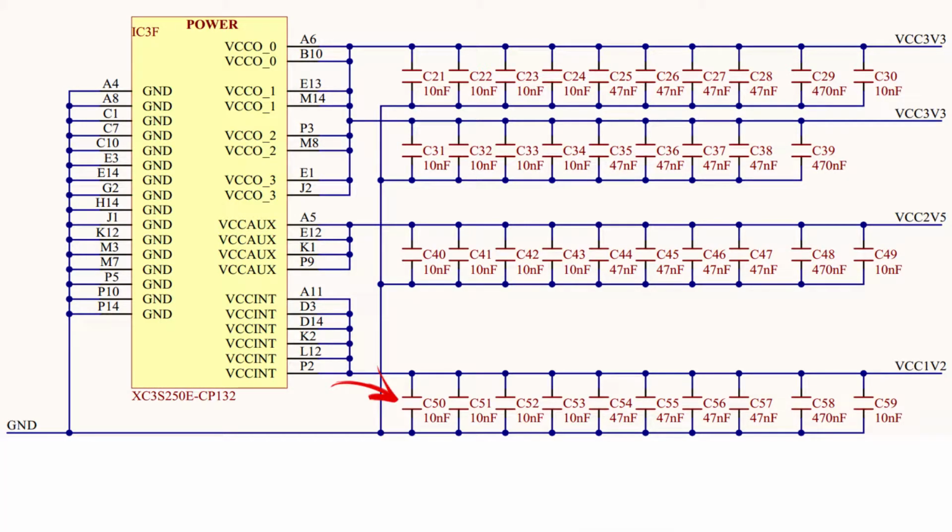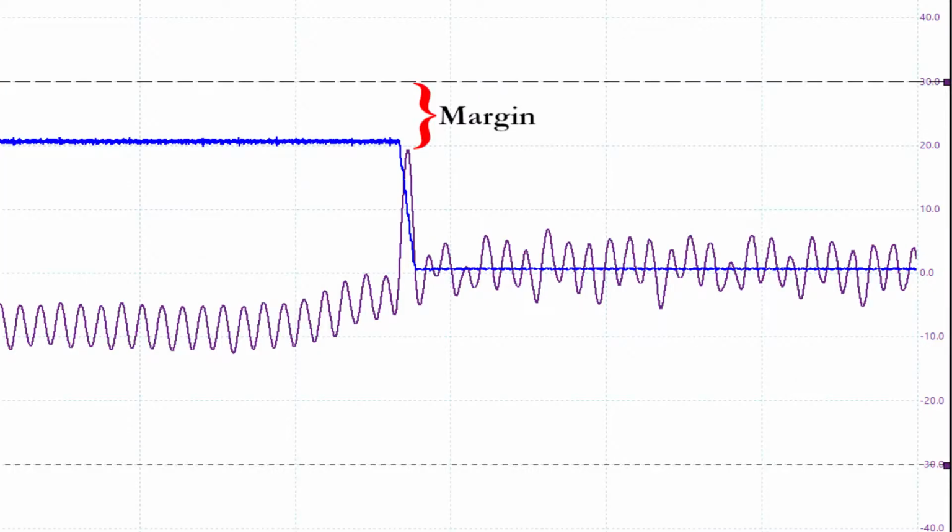If you find that your circuit is on the high side of output capacitance, try reducing either the value or number of capacitors, testing with the Loadslammer after each reduction to verify operation within specifications, and with minimal ringing and overshoot. Leave some margin so that the production and component variations don't push the performance beyond limits. Verify that the reduced output capacitance doesn't increase output ripple voltage excessively.